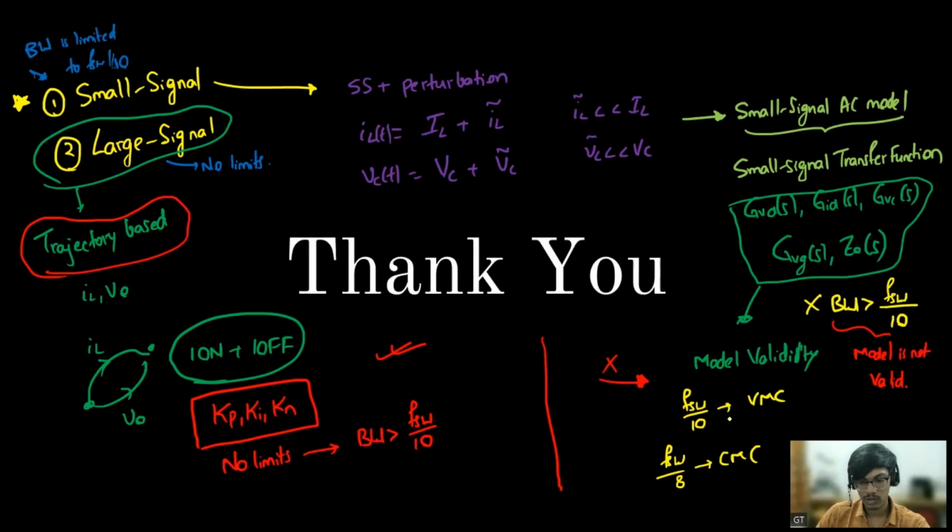So now I got those values. If I want to improve it, I can manually tune KP, KD around that ballpark. But in order to get into that region, I have to have some easy method to start with. So we'll start with the small signal, and you can manually tune around those values. Now my converter is working. Now the other requirement is to improve the response. How can I improve? If that small signal is sufficient, then my work is done. But if I want to improve it so that the bandwidth is more than 1/10 of the switching frequency, then I'll go for large signal tuning. So yeah, that is the method.